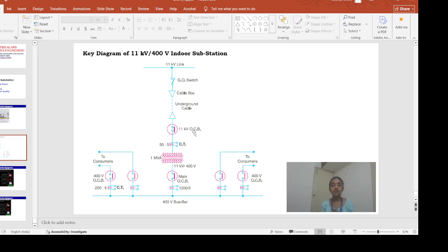Okay, so as I told, whenever the fault is detected, some ionized plasma or conductive arc will get generated, and due to that, the circuit breaker will try to extinguish that arc. Due to the generated arc, some heat is generated, and that heat is evaporated in the oil as a dielectric, which is separating the fixed contact and the moving contact of your circuit breaker.